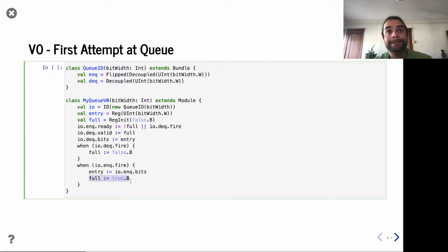And one thing I want to point out is that today, sometimes the way we write this code is going to look a little bit more like software code, a little bit less like the hardware you've seen so far. This is very much valid Chisel. We're going to see Chisel very much like this the rest of today, but unlike what we've seen before, the order of the lines now starts mattering more. For example, these lines could be completely reordered without any consequence, because they're simply describing connections. This is connected to that. This is connected to that.